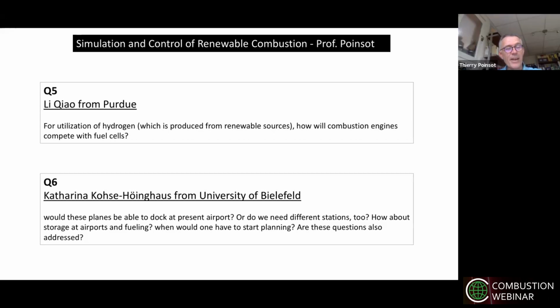Yeah, well, we had a very interesting meeting recently in Toulouse, where we had people from aircraft companies and people from rocket companies. The people from aircraft companies were saying, we're going to build an aircraft burning H2. And the people from the rocket companies were telling them, good luck, because they want to do it cryogenic. What you do in a rocket, which is cryogenic, is release the hydrogen when the temperature gets too high.